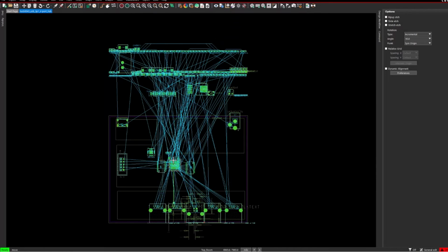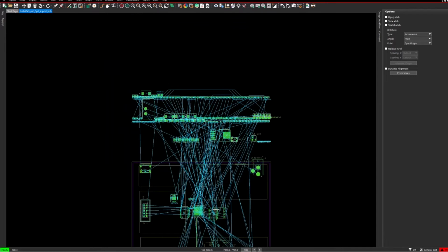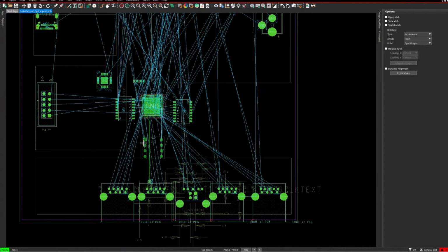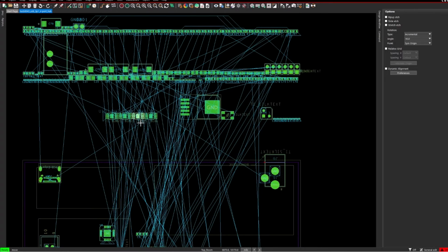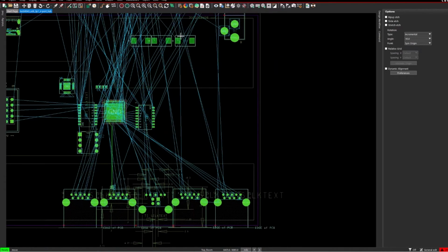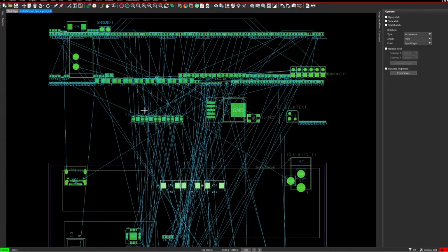It just means that depending on the rise time of the signals for your high speeds, if your trace carrying that signal is too long, it's going to start causing reflections and issues. So you want your trace to be shorter than the wavelength of the rise time of that signal. And this is just one of many techniques to make your board help the signal integrity out for free.